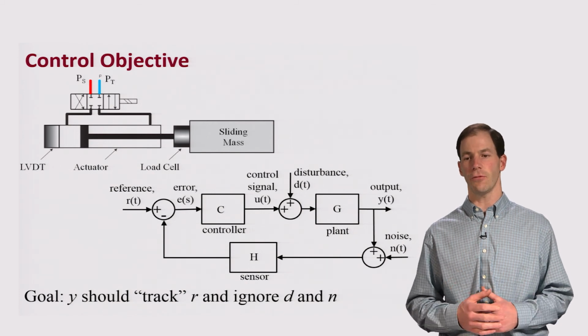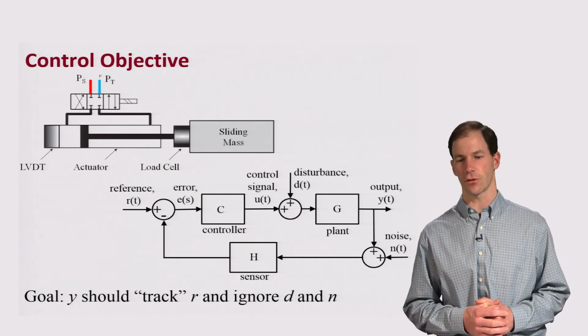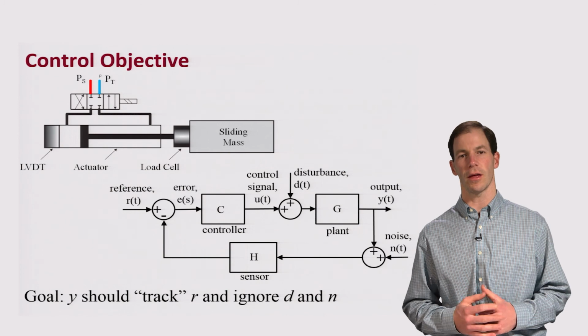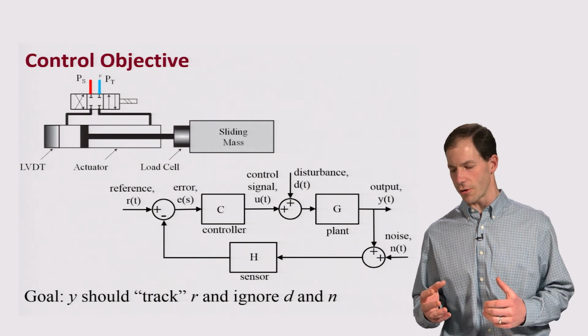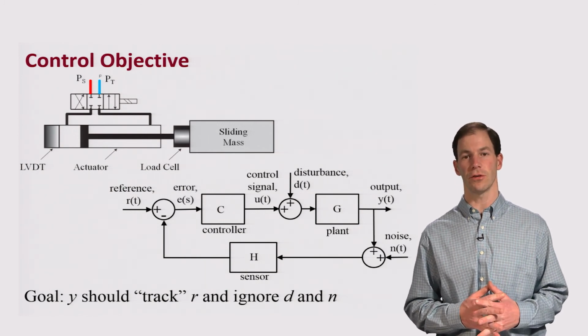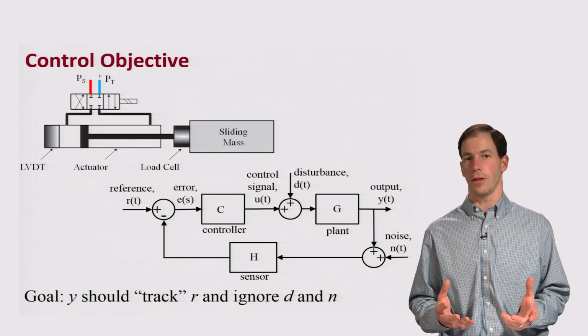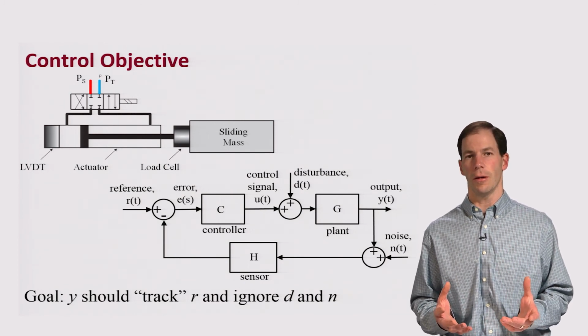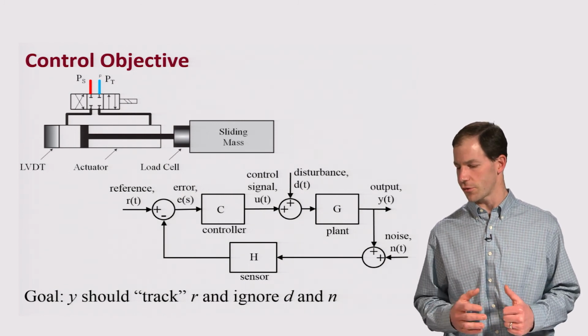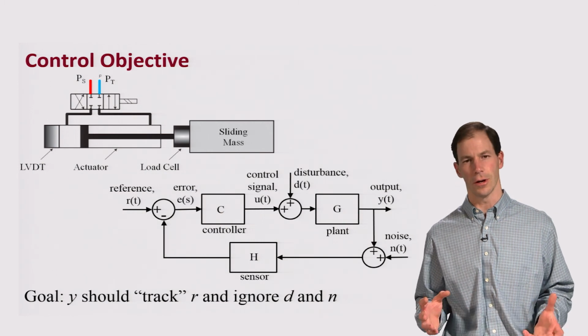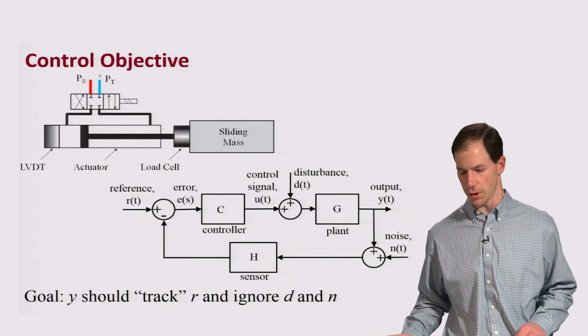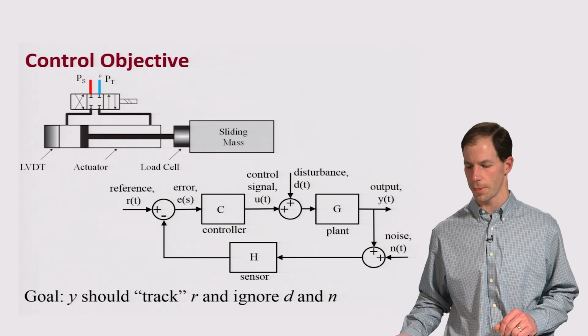Because of that, if we apply a large amplification in our controller, we are going to amplify that high frequency noise. So very often we want to achieve the specifications of the system, but make it no faster than that, because then we'll start amplifying this noise. So we've got these trade-offs that we need to make as we're designing our controllers.